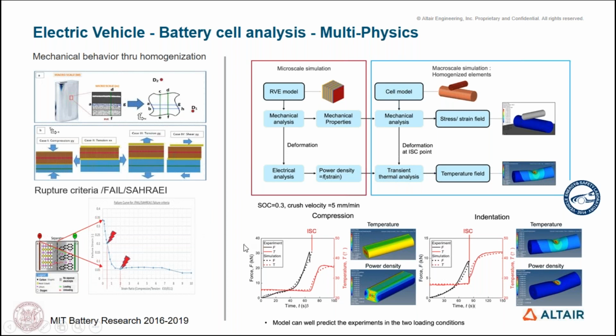One of the papers we have published along with the MIT battery research between 2016 and 2019, where we set up a complete workflow for this, checking all the mechanical analysis as well as electrical analysis. You can see a couple of the tests we did, the compression test and indentation test. You can see the experimental results, where we calculated the forces as well as the temperatures, and then the simulation results, where you can see the forces and temperatures. There is a close match between the virtual and actual physical test.